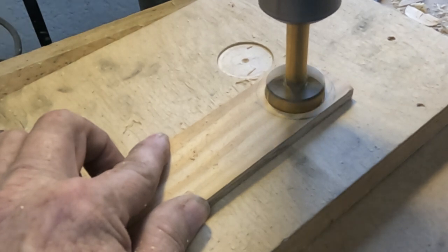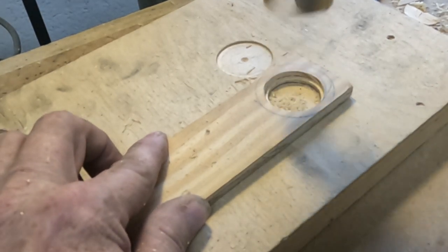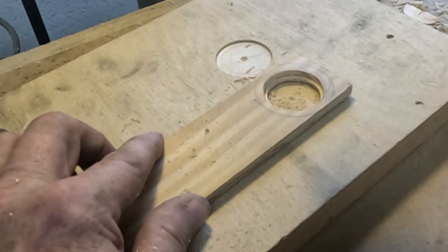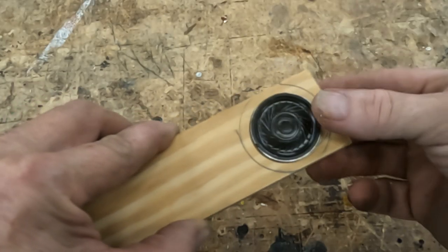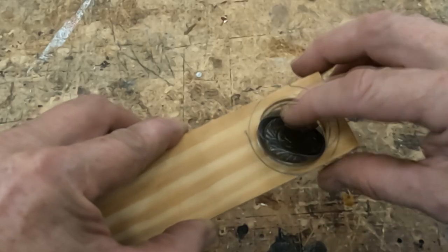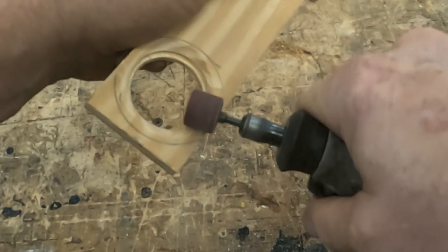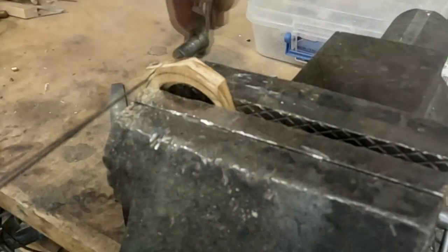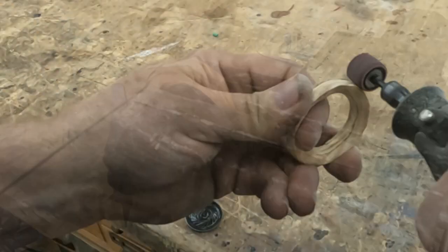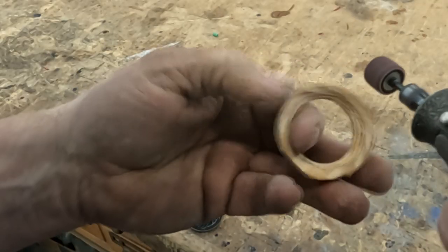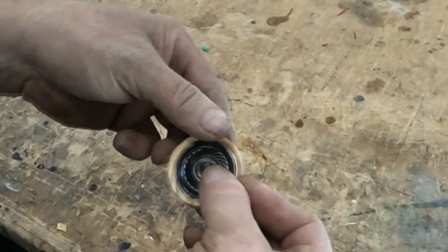Be aware these measurements may vary if the sound module manufacturer provides a slightly different speaker, so you need to verify the size. The speaker will drop inside the outer hole and rest in the smaller hole. Use a Dremel to shape the wood into a bowl. Then cut out the outer ring and file it to match your tracing. Finally, trim the edges smooth with the Dremel. The speaker is now ready to glue in place and install.